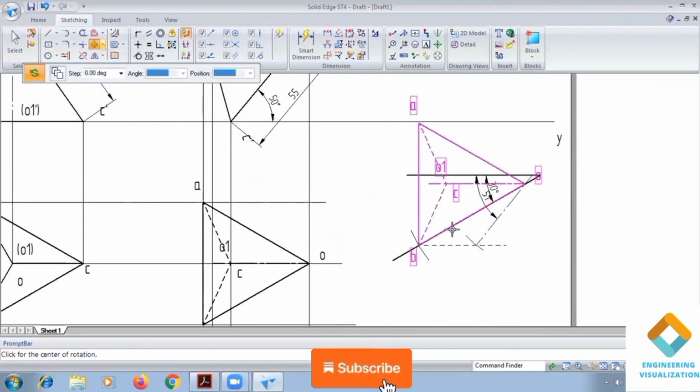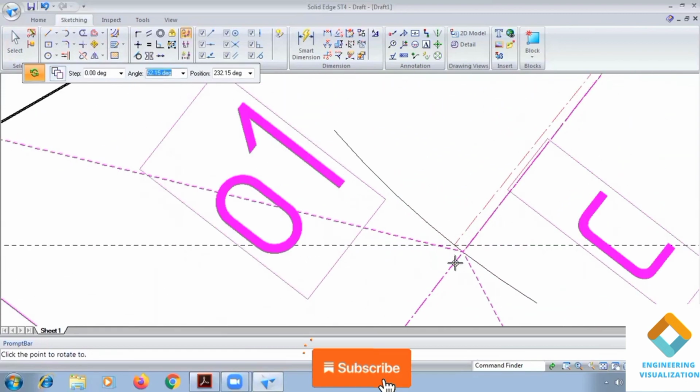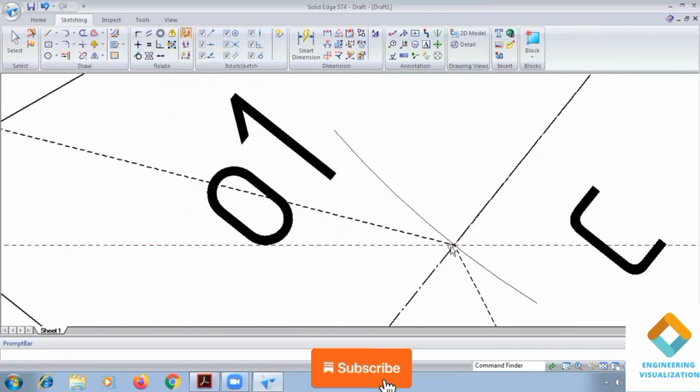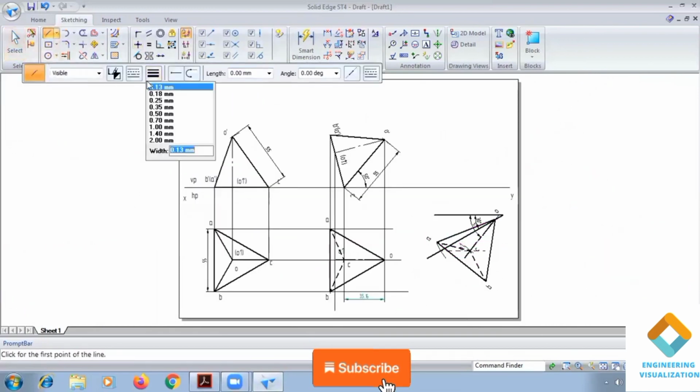So using the move command we have copied. Take the reference point of OC and place it on the angle line here. Place it pinpoint. You can zoom in when you are placing it. Now draw the projection lines to complete the final position here.